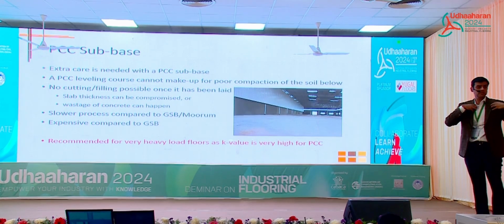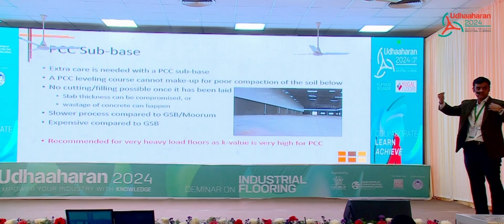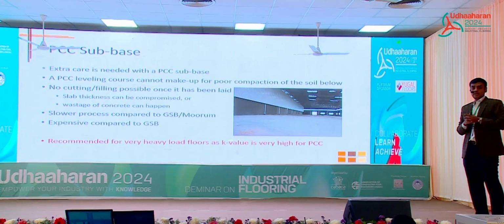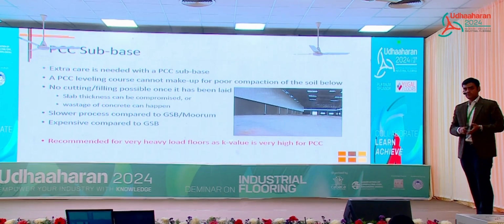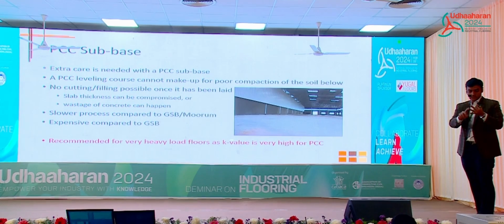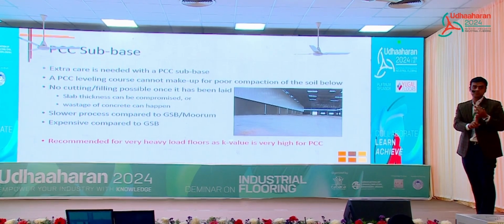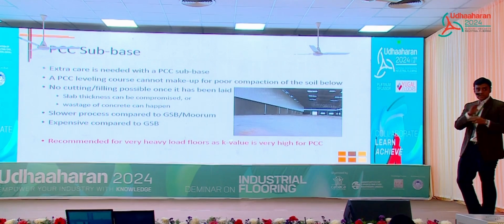So what we do typically is, before constructing a slab, we actually check levels at every 3 or 4 meters, and wherever there's a high spot, we cut the high spot. Wherever there's a low spot, we fill it. That is very easy to do with a WMM, WBM, GSB or Muram. That is not possible with PCC. Once you're done with PCC, you're done.